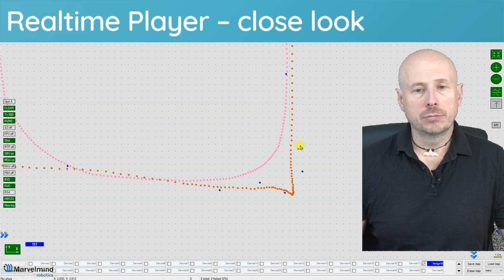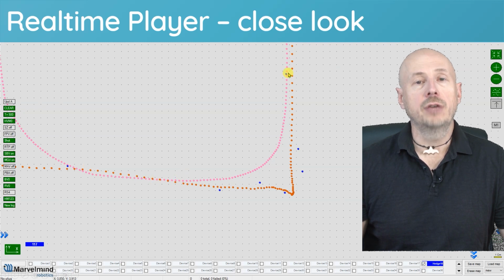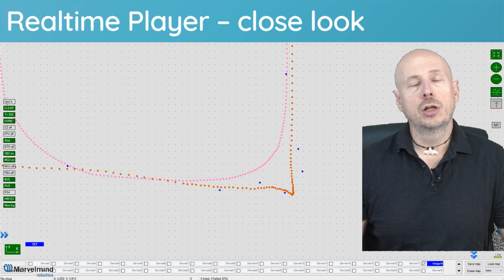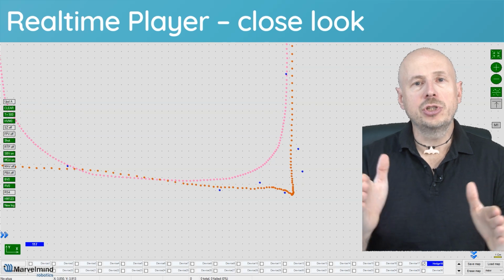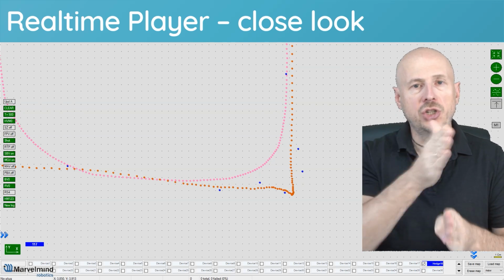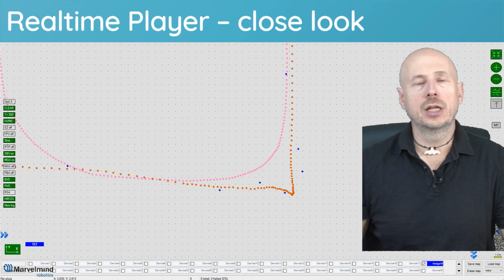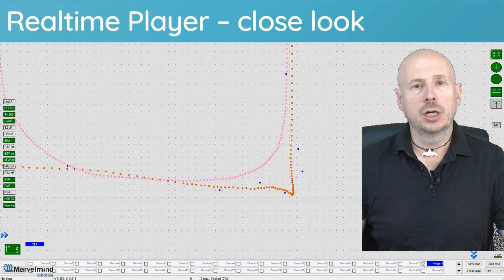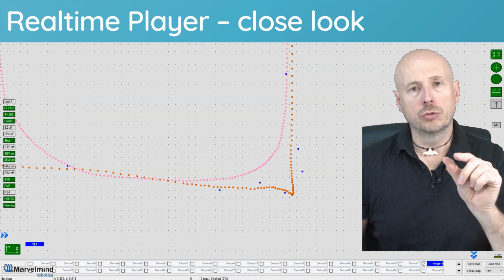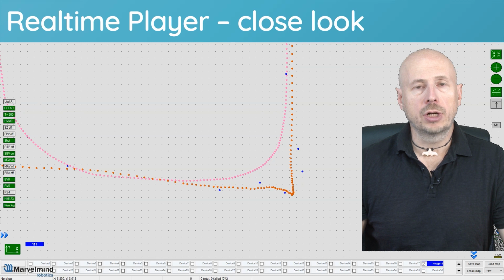And this is a close look. Well, basically this is already 1 centimeter, so you can calculate roughly 5 centimeters error due to real-time player. But again, in these areas it helps a lot and it makes it even smoother, and the error is already lower. It's very difficult to calculate, but you can see it's basically reducing the jitter or spreads the jitter of ultrasound, making the location updates 100 Hz, and at the same time the spot smaller than 2 centimeters, so better than the original ultrasound.